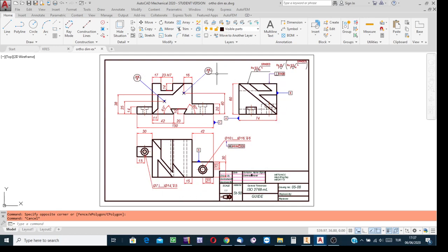Reading, saying reading, we mean looking at the views, reading an engineering drawing. What does it mean? Look at the given orthographic views, and also see the associated dimensions, and then start seeing the object in your mind three-dimensionally.